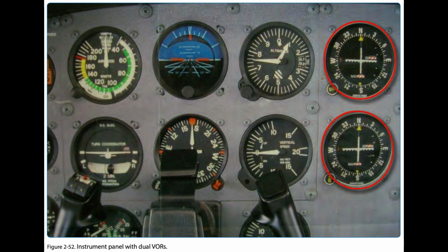NDB accuracy check. The pilot must identify an NDB before using it for navigation and continuously monitor it while using it for an instrument approach. The lack of an ident may indicate that the NDB is out of service, even though it may still be transmitting, for instance for maintenance or test purposes. If an incorrect ident is heard, then the NDB should not be used.